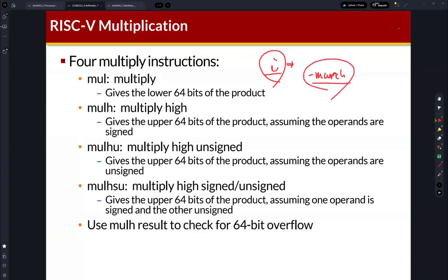I don't remember the exact name, but after these options we define rv32i, okay? So it means it generates a compiler which only includes the rv32i instruction set. So if we use multiplication in our C code, the multiplication is translated into some other instructions, right?